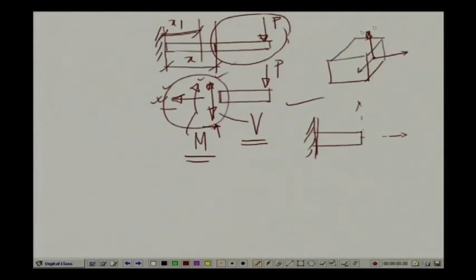So, to match this criteria, our axial force on this particular section is positive on this, the shearing force is positive over here, and the moment which is anticlockwise, the perpendicular to which is projecting out of the plane, we call them positive.